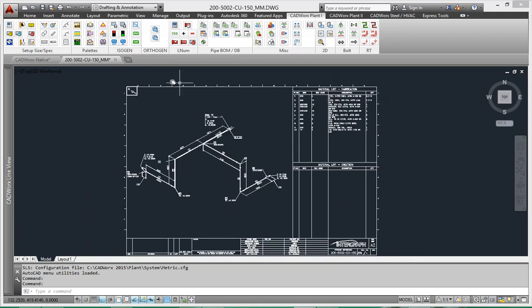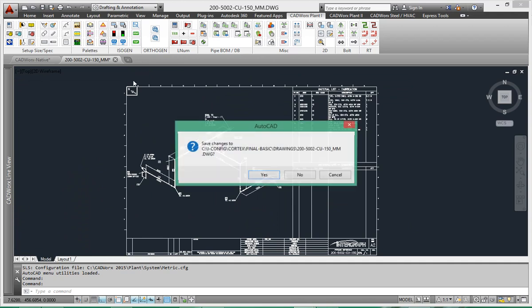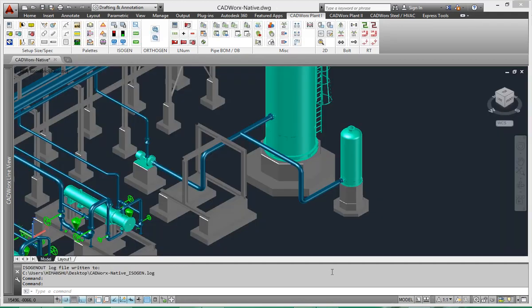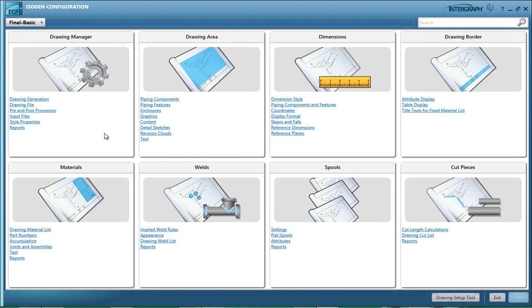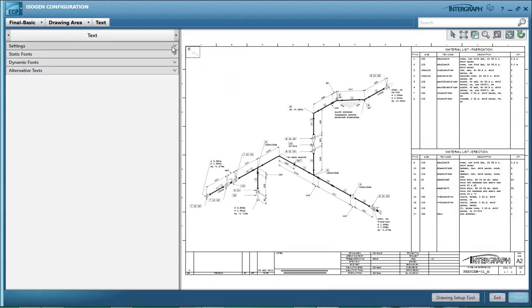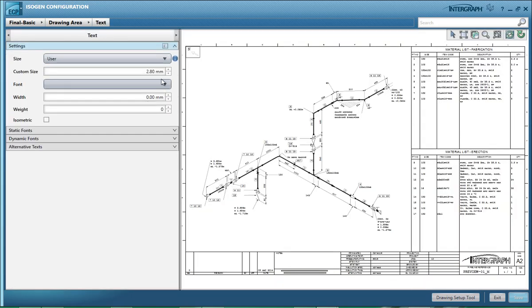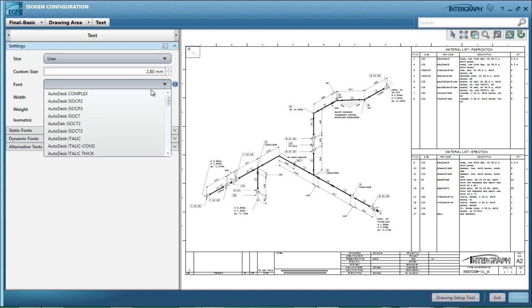So what went wrong? Before we apply any fonts to bill of material or attributes, we need to assign the default font to the entire style. First, we go to the settings for the drawing, where we can set the fonts for the entire style, and then we can assign fonts for bill of material and attributes individually. Let's check the fonts for the entire style here. If I check the settings, we haven't assigned any fonts here, so that's why it didn't appear properly.